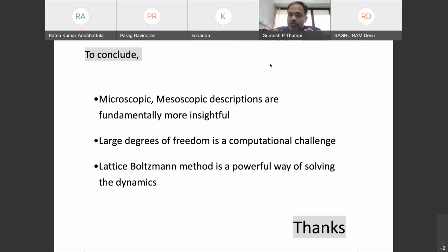Even in Lattice Boltzmann, you typically do it with a Cartesian mesh, but still, the way the probability equation is written, if you look at it from the point of view of that equation, it's actually quite easy to impose the boundary condition on the surface of the particle, and depending upon where you specify that boundary condition, you're actually specifying where the particles are, what is the shape of the particle, and so on. Does that answer your question? Yes, sir.